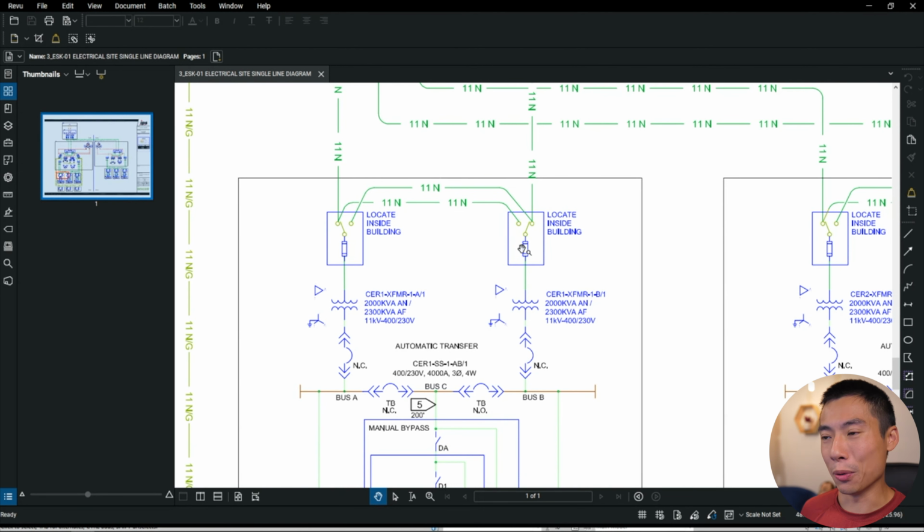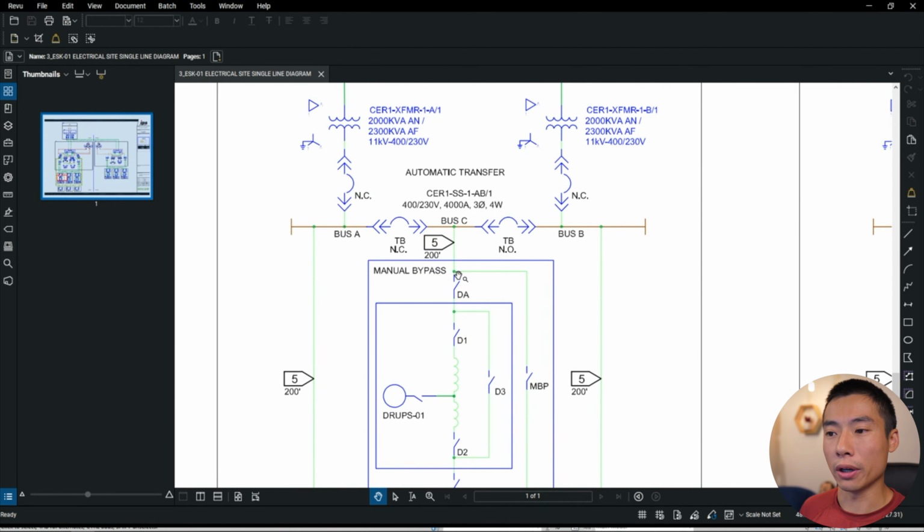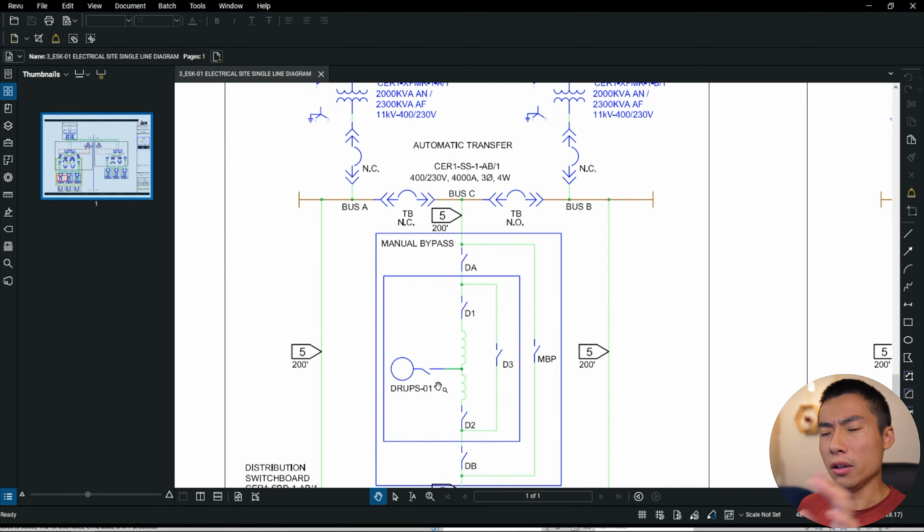This is a crazy bonus cut, but anyways, we have two feeders coming in, we have a switchover, a double-ended substation with two tie breakers, and then the two tie breakers went into diesel rotary UPSs. Actually, I think we downsized to one. It used to be two per building, which was nuts. But we come off of the center tap of the substation to a diesel rotary UPS for the entire building. What that means is that the entire building is on UPS power, and UPS power is non-interruptible.